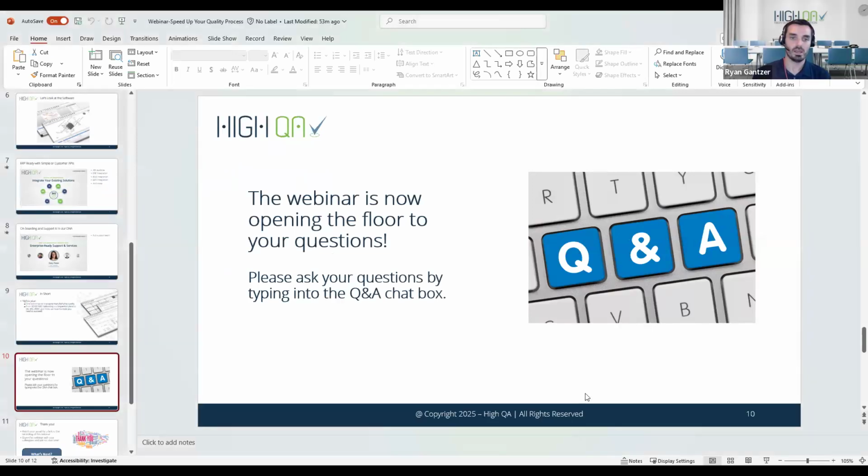So we have tables in the background for tolerancing. So if you remember, I showed that plus-minus dimension. If the tolerance is called out on the drawing itself, we'll bring that in. If it's not, that's where we have tables in the background, which can be customer specific, part type, part family specific, however you want. It can be a range table or a decimal table.